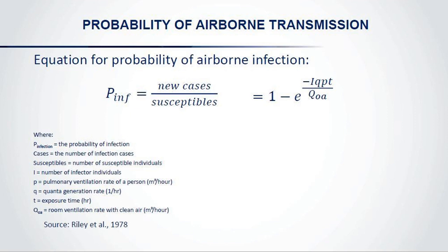So from that, we can calculate a required ventilation rate equivalent to the transmission rate, that's R0E, for any limiting disease transmission rate, for any specific disease. So if I say I can tolerate a 1% transmission or 5% transmission, I can put that into R0E. For the disease Q value, that's a quantum generation rate, I can plug TB in there. I can plug different strains of TB, with and without treatment, COVID, etc. I can put in the number of occupants, size of the room, exposure time. If it's a waiting room of 4 hours, we can plug that in there.